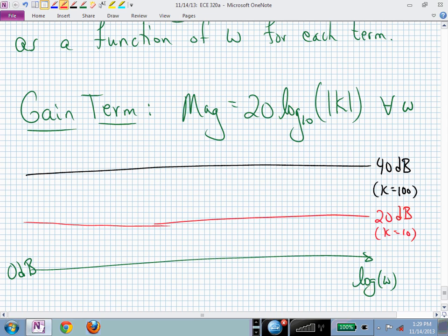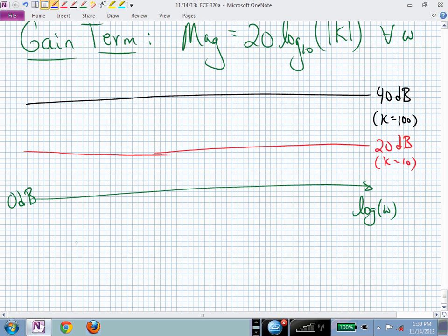And the reason we're doing dB is because when we're doing logs, then we add numbers instead of worrying about multiplying. So we can look at each of these factors individually and add up their contributions since they're in dB and not have to worry that they were actually multiplied together in our transfer function. Since we're taking the log, now we just add up all of these individual contributions. In this example, we just have a gain term and a linear term, two terms that we have to add up. If somebody said, oh, you know what?